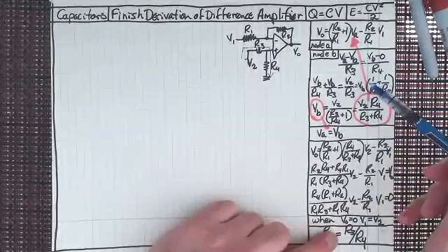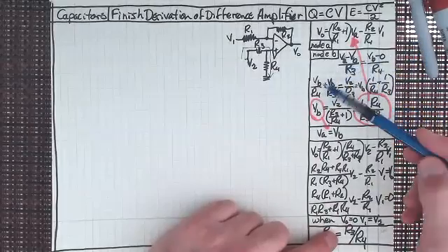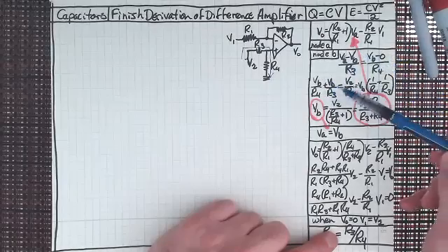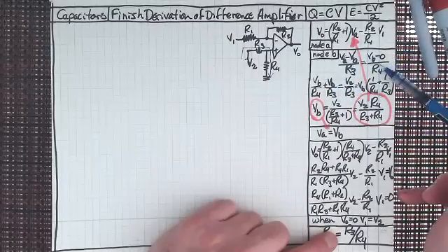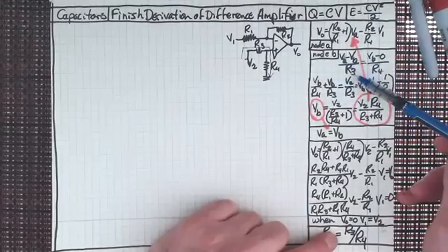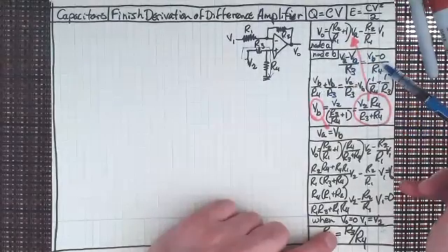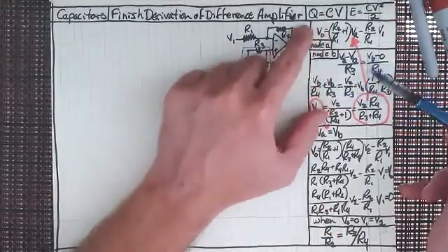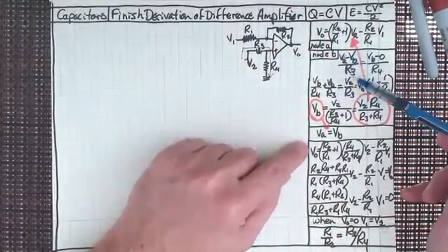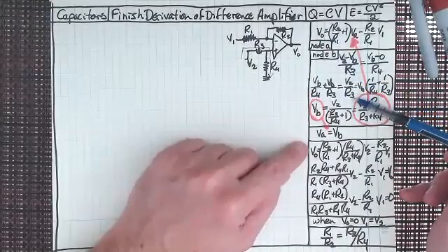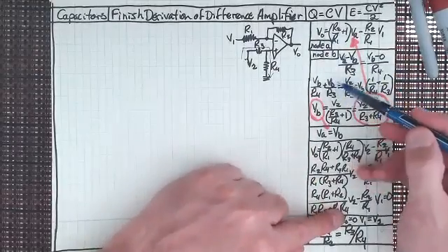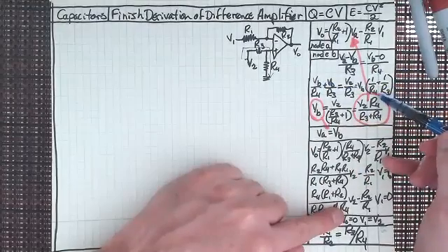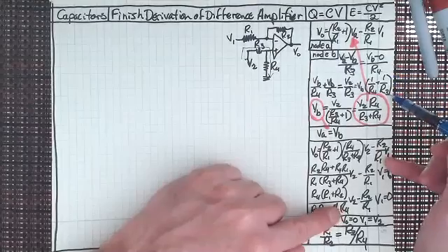So when we expand this out, I've got V sub B over R4. I've just taken that, leaving it on the other side here. I'm bringing the V sub B over R3, which is negative, over to this side. So that makes it a positive V sub B over R3. And then on the other side, what am I left with? I'm left with V sub 2 over R3. And now, if I take V sub B out of there, I've got 1 over R4 plus 1 over R3.